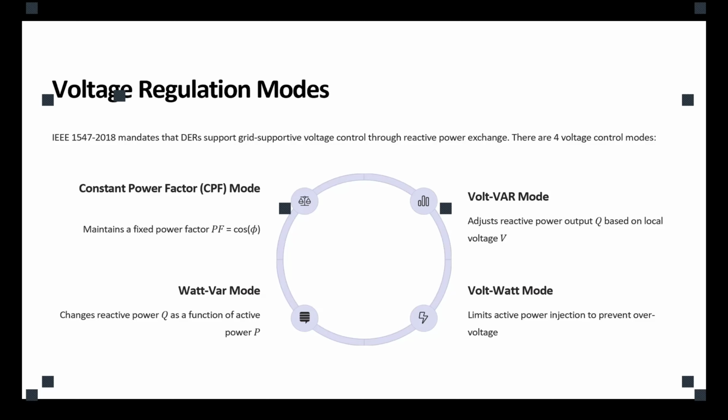So we keep the voltage regulated and at the same time try to optimize the power factor. Again, it could be implemented from another perspective, voltage-watt control. When you control the voltage, you are basically controlling your reactive power, but at the same time you are controlling the active power, the watt, so you keep the power factor stable.